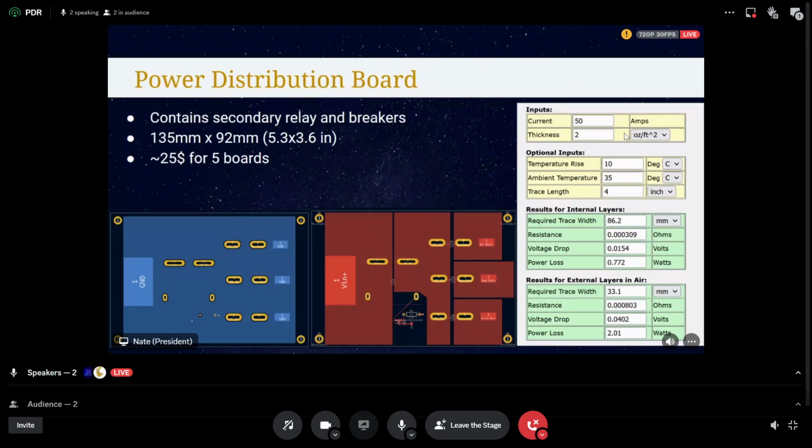And then as far as temperature goes, it is always concerning when you're putting more than like 5 or so amps through a PCB. So the general protocol is to use planes, right? Everywhere you see this red, this is a ground plane, that's the negative return path, and then the red is all power, the active path there.